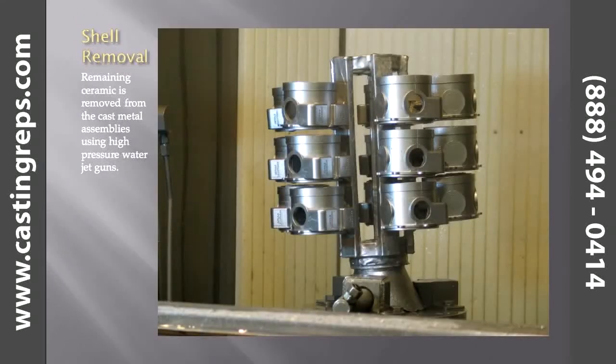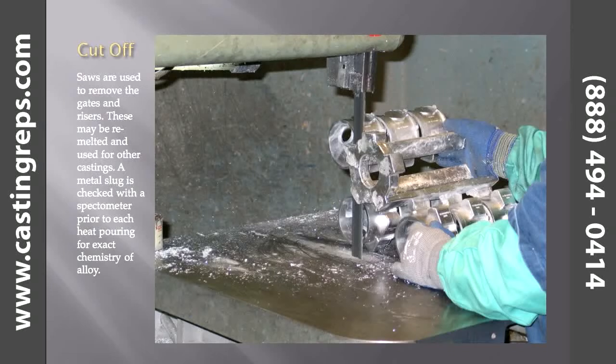Shell removal. Remaining ceramic is removed from the cast metal assemblies using high-pressure water jet guns. Cut-off. Saws are used to remove the gates and risers. These may be remelted and used for other castings. A metal slug is checked with a spectrometer prior to each heat pouring for exact chemistry of alloy.